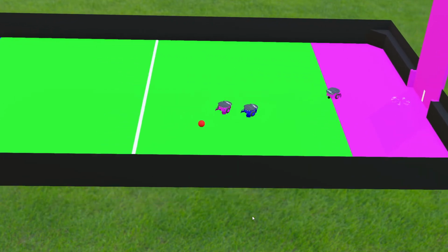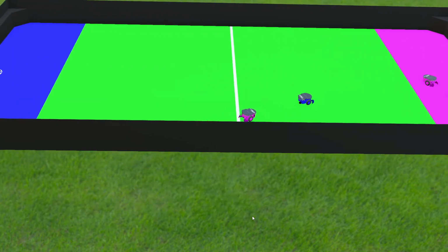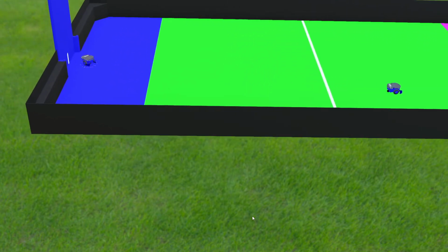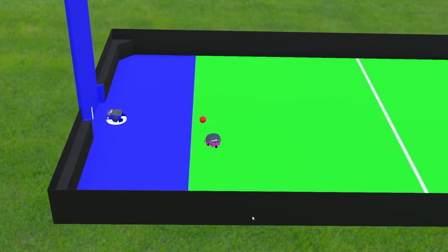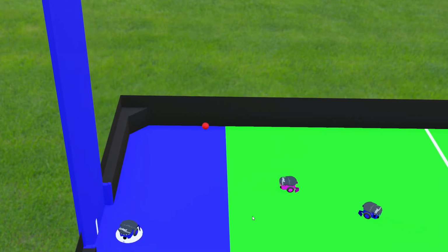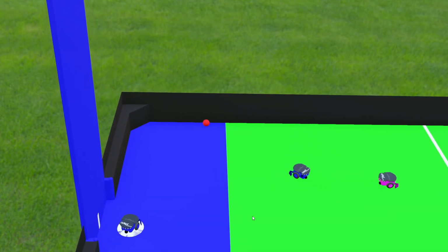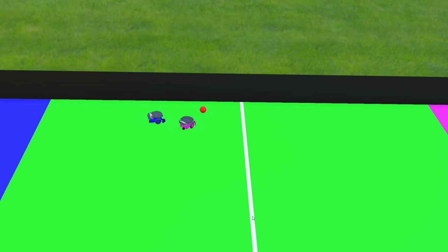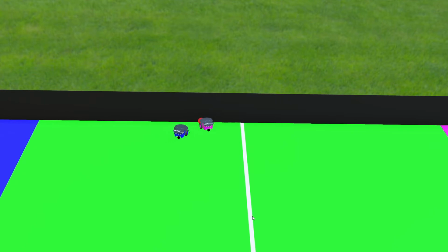And then when it senses an object at a certain distance in front of it, it'll trigger the next state, which will then turn it directly towards the wall on the side, and then it will look at its front and rear sensors, and look at the difference between the two, and then will drive forward or reverse to try to get these values to match. If that value is too negative, that means it has to reverse a long distance, then it will actually flip its bearing 180 degrees, so then it will turn around the opposite way, so it'll drive forward. That's only a temporary measure.